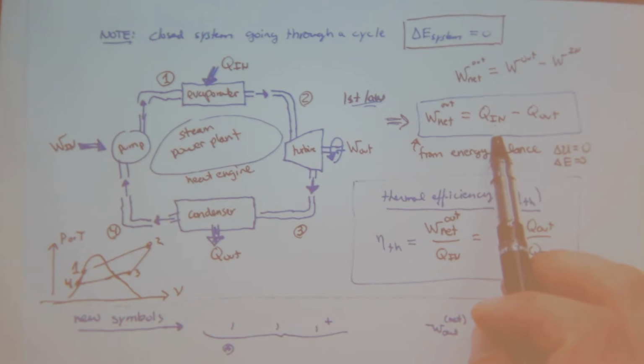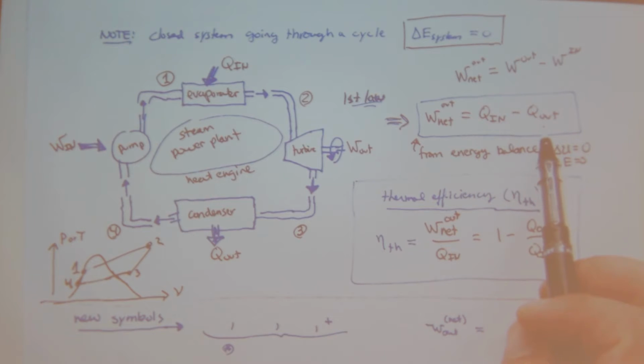And so the heat engine, its total net work out is going to be dictated by, so of course I can put more heat in if I'm next to a volcano versus the engine of a motorcycle, right? And I can suck more heat out if I'm using an ocean relative to my bathtub, right? Now of course the motorcycle engine doesn't really act as a reservoir, it's too small, but a volcano would. And the bathtub, okay, if I have a micro cooler the size of my thumb, then the bathtub probably works as a thermal energy sink. But to a power plant, the bathtub doesn't work at all, right, for a sink.